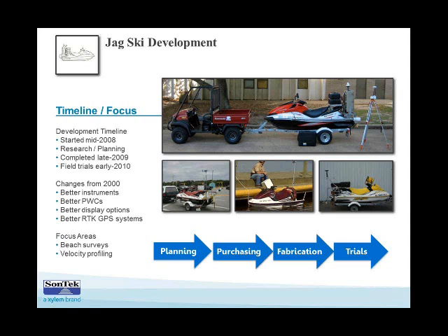So we went and did some updated mapping for bathymetry, but then we also did some velocity profiling across the rivers and some of the smaller tributaries as checks for the hydrodynamic model to validate and/or calibrate it as necessary. So this project involves some tide gauge installation.